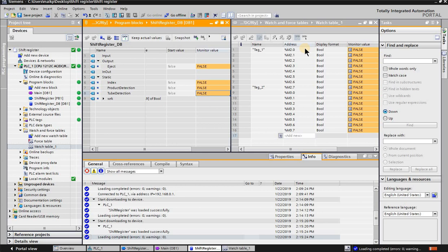the address word has 2 bytes in it, and it's a little bit different because the word is not like a byte. So the word actually starts on the left side. So you have 2.0 through 2.7, and then the next one on the right side to it would be 3.0 through 3.7.